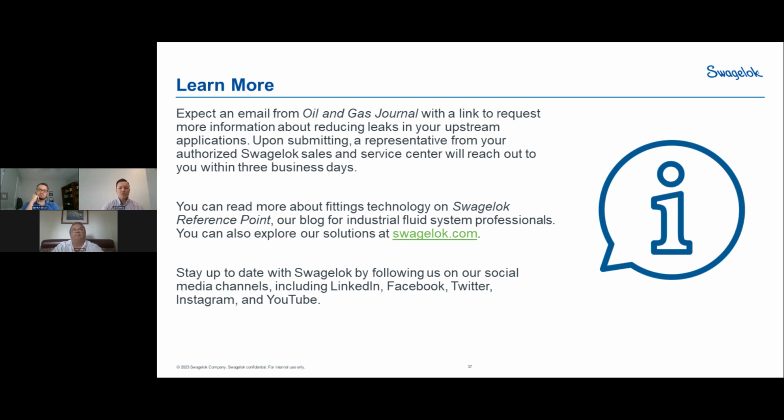So certainly I would say there are great resources on Swagelok.com. You can find both of those, the Tube Fitter's Manual and the Pocket Guide, with extensive tables based on tubing size. And then also just think through the entrapment areas that could exist in a tubing clamp to make sure you don't inadvertently run into a long-term corrosion issue while solving the vibration problem.